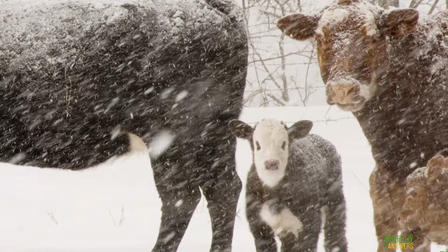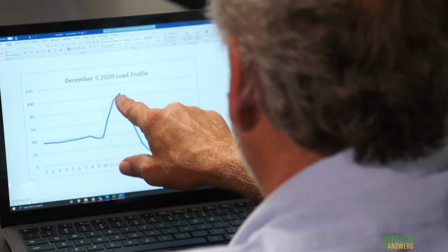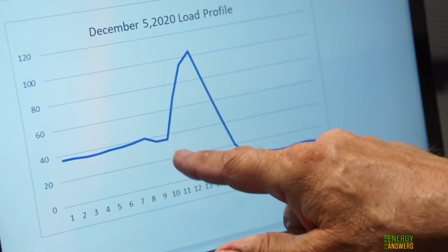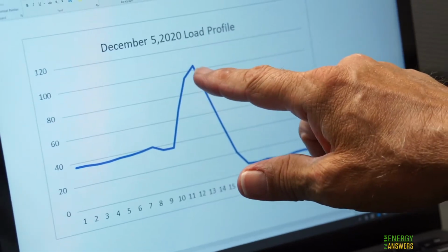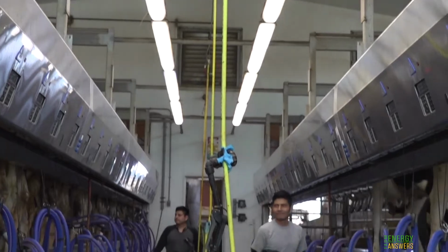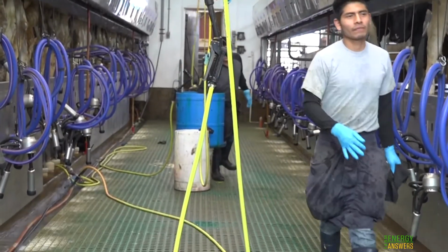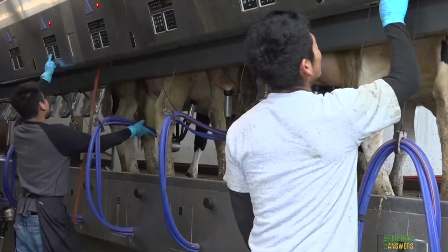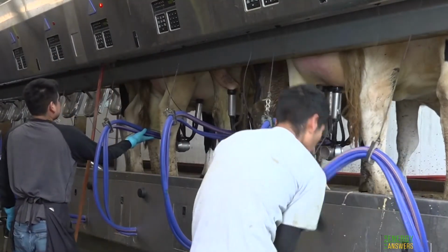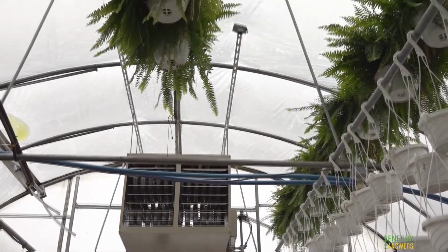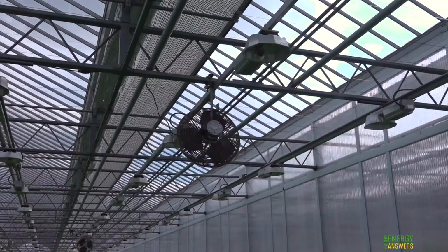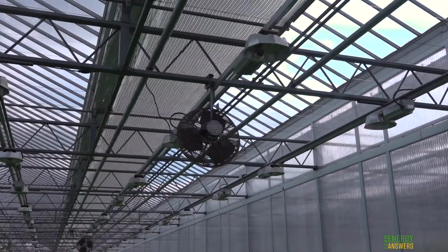Think about your EUQ as consisting of two components: base load, the amount that is used every day, and variable load, the variable usage that depends on outdoor temperature and other factors. Typical examples of base load include lighting, milking pumps, and hot water for daily washdown. Some farms' EUQ, such as dairy farms, will be mostly base load. Other farms, such as greenhouses, could have a very low base load since most of their energy use is usually composed of winter heating and summer ventilation.